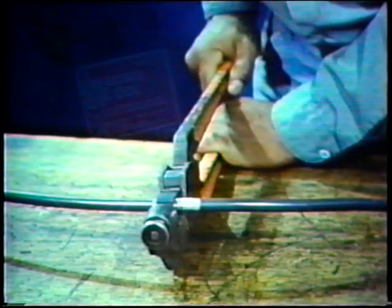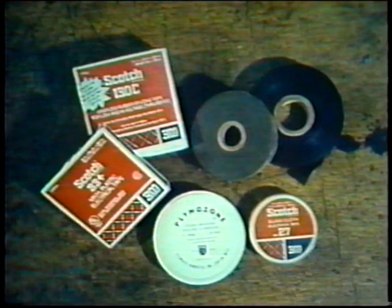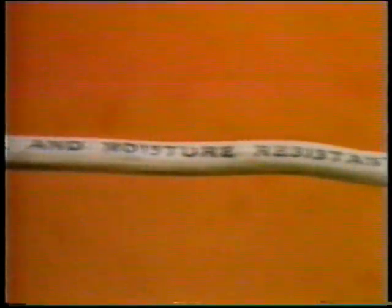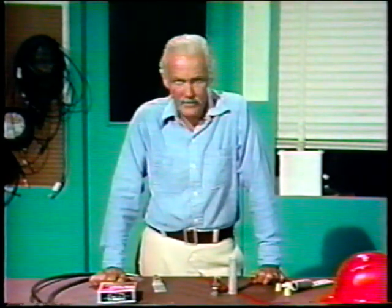To complete the splice, Bill has to insulate it. He'll use electrical tape for this. The electrical tape will replace the insulation that was stripped off the conductors. Here's an example of the kind of information you'll see stamped on a conductor. This is marked 12, type TW, oil and moisture resistant, 600 volt. Well, when you go to replace this insulation, you'll want to be sure that the tape you use has the same qualities that the original insulation does.